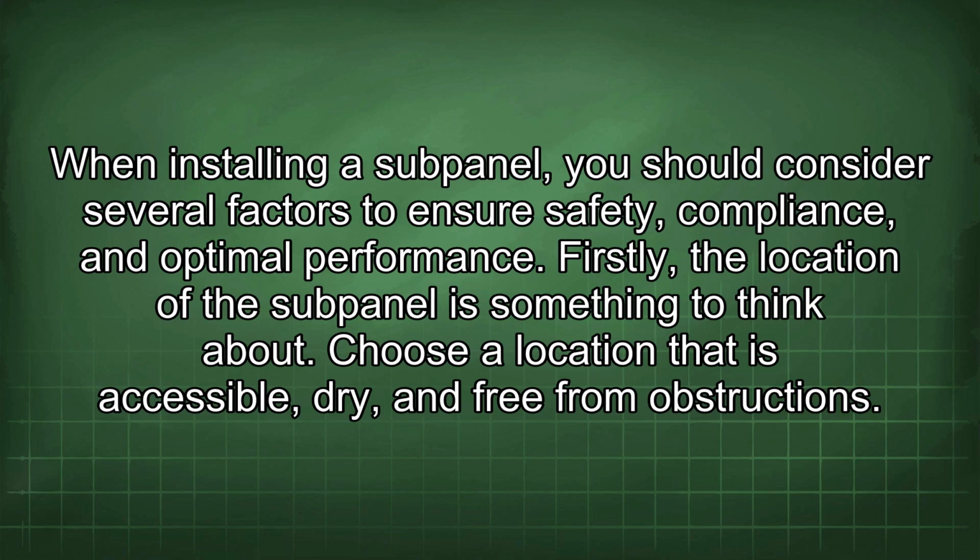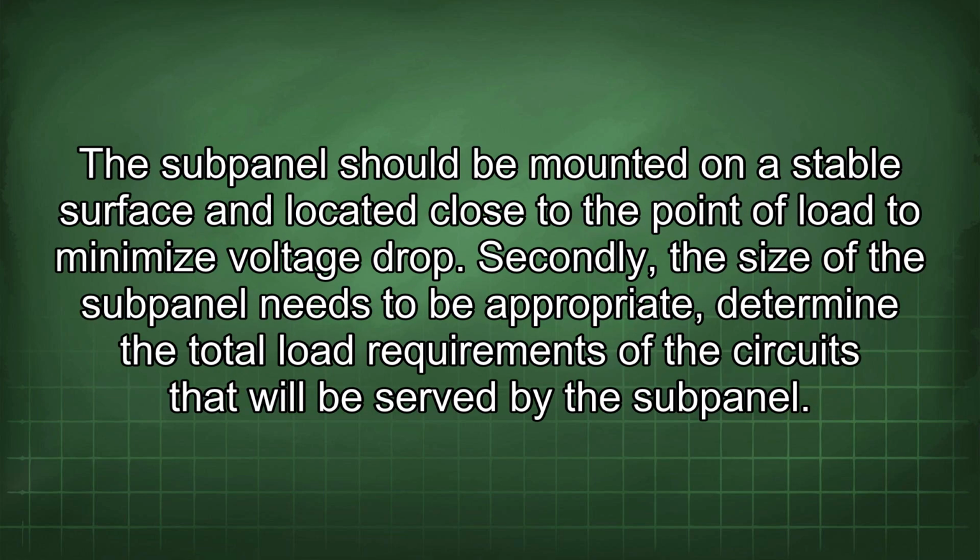Firstly, the location of the subpanel is something to think about. Choose a location that is accessible, dry, and free from obstructions. The subpanel should be mounted on a stable surface and located close to the point of load to minimize voltage drop.